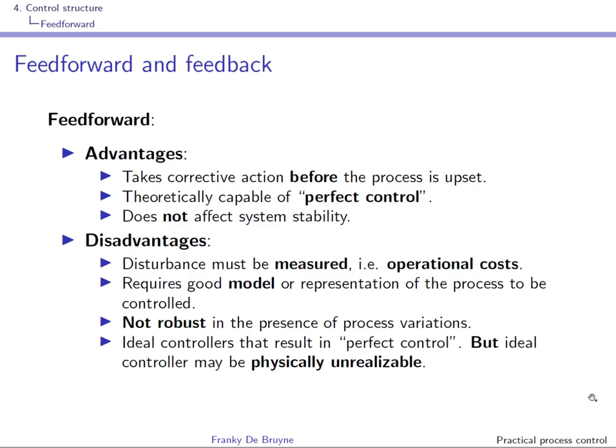Feedforward comes with an operational cost in the sense that you need an extra sensor to detect the disturbance. A good model of the process is required to implement feedforward. And indeed, we need a model of the process, and we also need a model of the disturbance dynamics to implement the feedforward action.